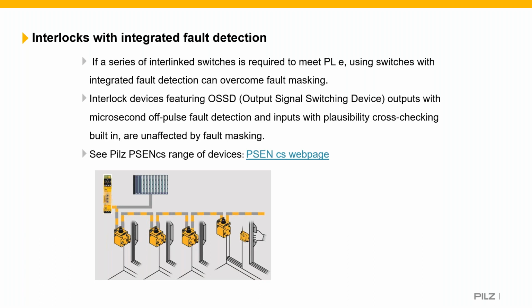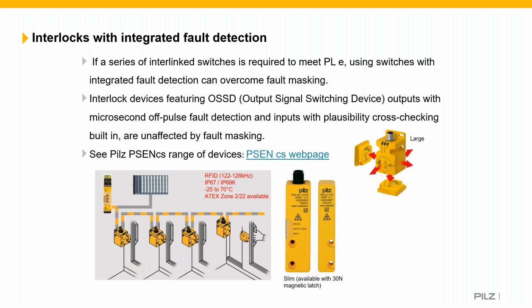So this switch here is checking the output of that switch, which is then checking the output of that switch, etc., back to the safety relay,